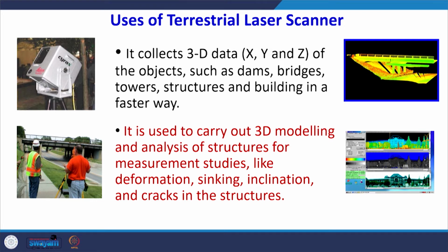Once you are collecting this 3D dense data with the help of the device, which is almost automatic, because you have to define the extent and then the scanning will be done automatically. It will scan the whole of the structure in an automatic manner and will provide you point cloud 3-dimensional data, and from that point cloud data you can recreate the geometry of that figure, you can create a 3D model of that particular figure and carry out very precise measurements. So, measurements in terms of the depth, measurements in terms of the volume, that also can be carried out.